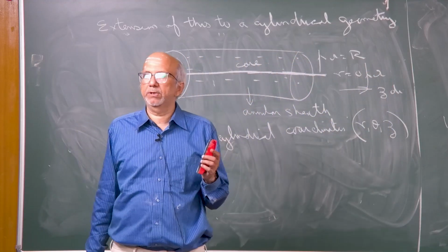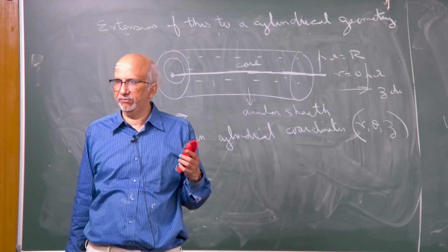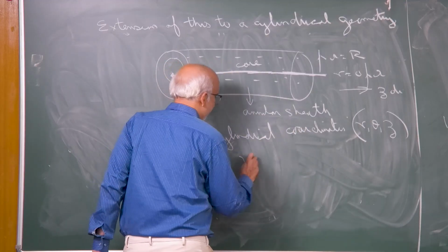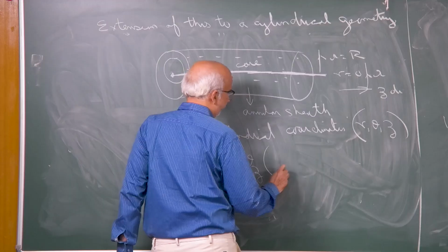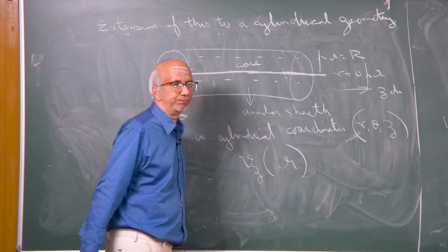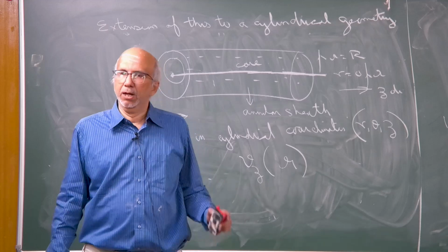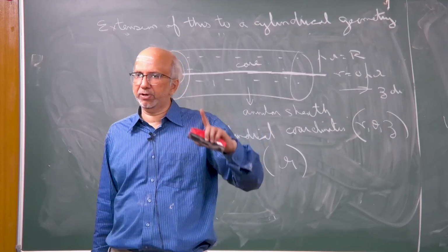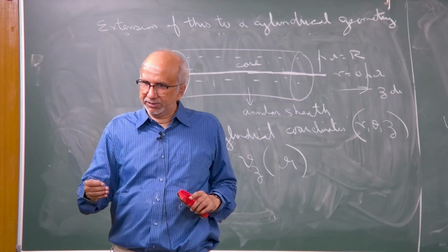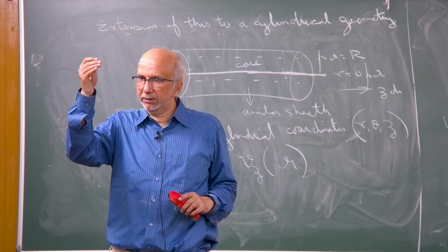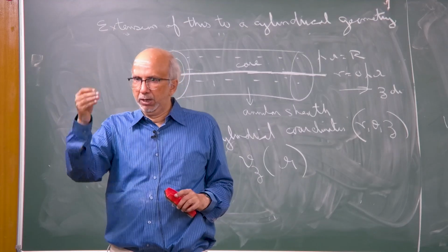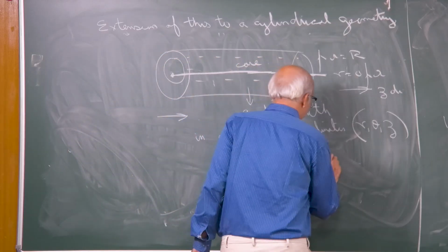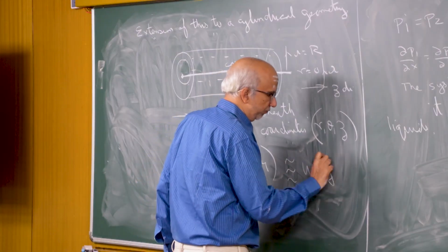Clearly, the velocity component which is dominant is going to be the Vz. This is equivalent to my u earlier. Vz is my velocity component and is a function of r. We had u1 as a function of y earlier. So, now we have Vz as a function of r, because it will vary in the radial direction. In the radial direction, velocity is 0 at the solid wall, and it is some value in the middle. So, this is similar to u1 as a function of y.